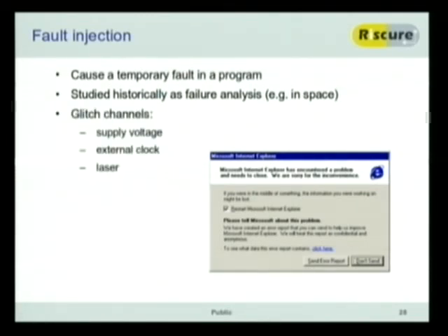And there are different channels that you can glitch. You can glitch the supply voltage of a chip. You can glitch the external clock, which is on smart cards, where the clock is provided externally. And you can go into the cool kind of laser glitching stuff.